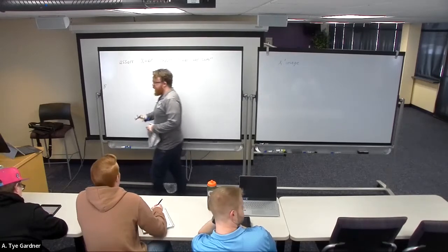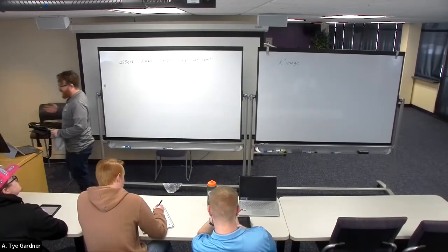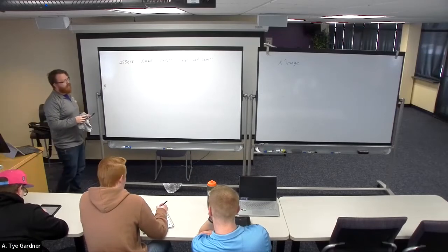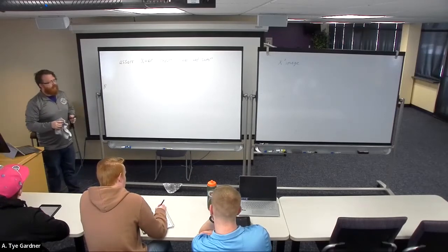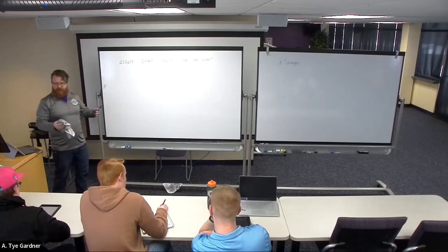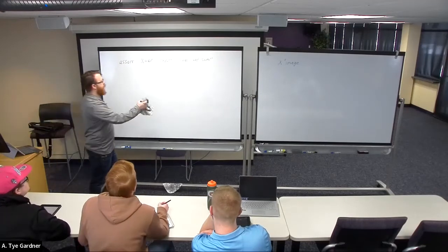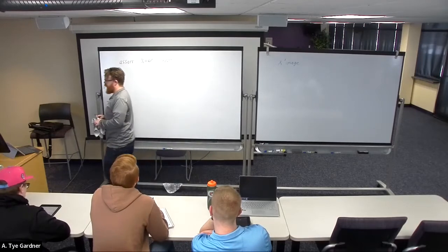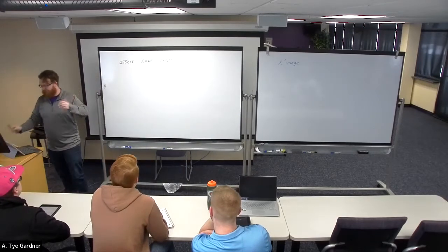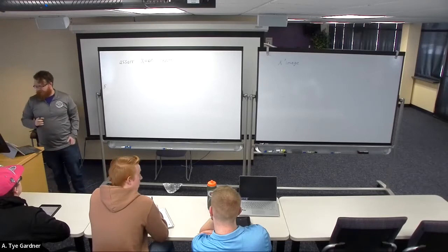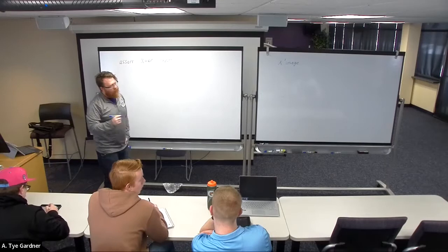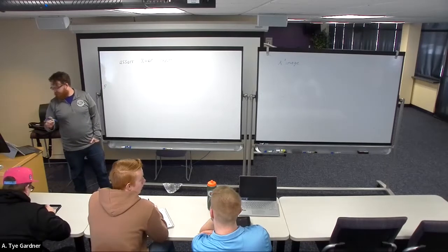Now, be careful in that this works really well for bits and standard logic. It won't work for standard logic vectors. It does also work for integers. So we'll get to how we do this with standard logic vectors in just a moment. But we can say, if x is supposed to be alpha, and I want to report it, then I can report, well, let's see, which one am I going to do first?